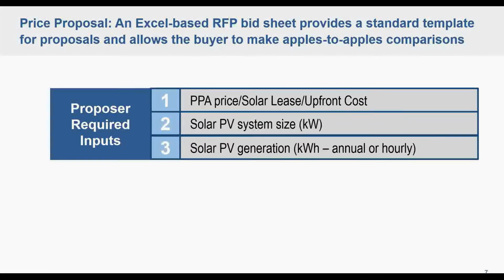In instances where your electric rate might be a time of use rate, it matters when the solar PV system is generating how much value it has, or perhaps the solar PV system size is large enough that a lot of time through the year it's generating more than the site load. So there could be some nuances around net metering credits and how that works. So depending on how complex the analysis is going to be, depends on whether you'd require annual or hourly data.